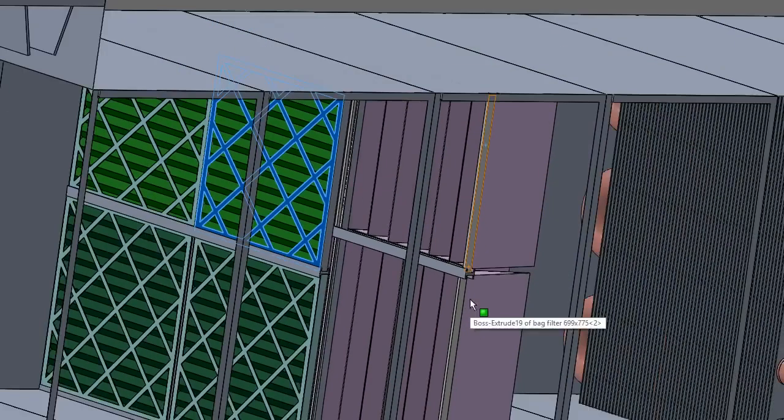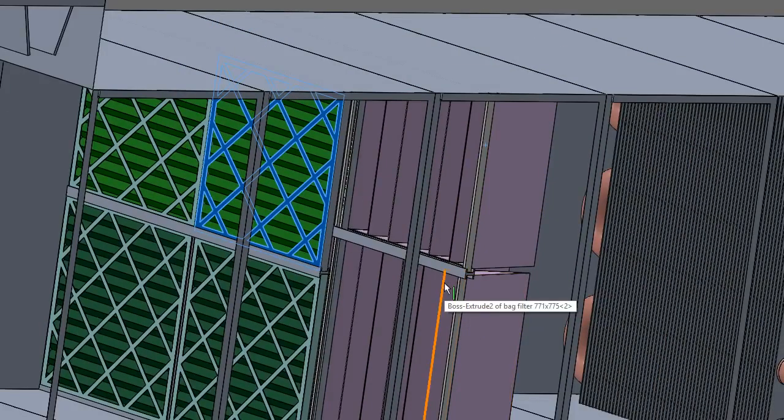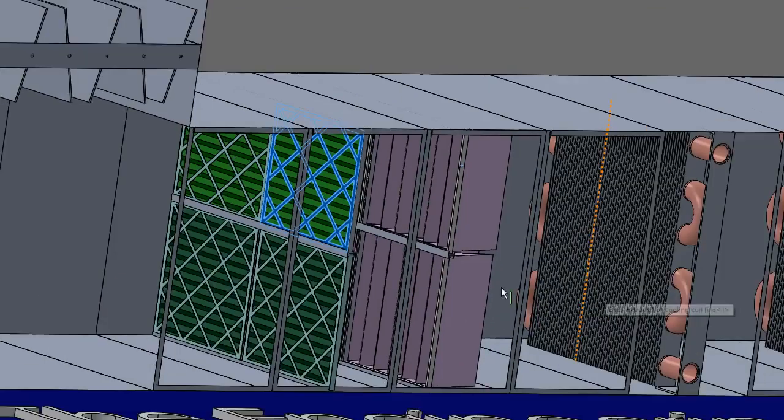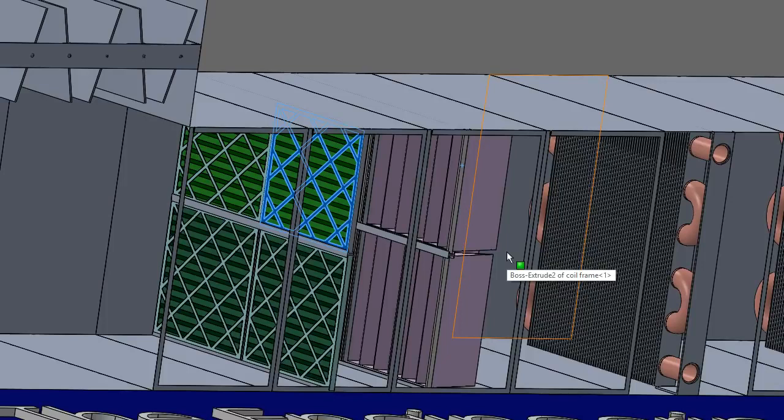And there is a surprising amount of dirt and just muck that comes in with the air, and you want to get rid of that and filter it out before it hits the coils, and also before it goes into your fan, is sucked in by the motor for the cooling, and is also pushed out onto the floors for the occupants, for the tenants, the office workers. They're going to be breathing this air in, so it's important that that air is cleaned and is conditioned